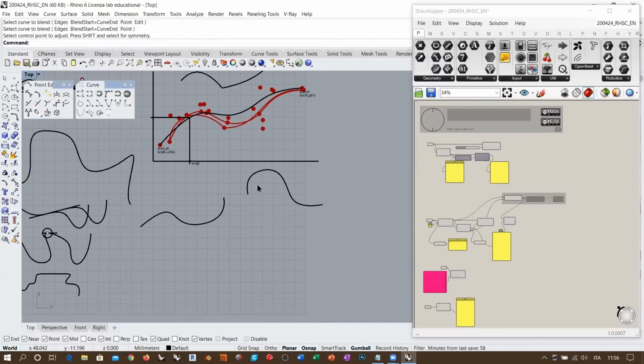So the only direct control that we have over continuity when working with the control point curve directly is over position continuity, so G0, and tangency continuity, which is G1. I repeat, for architectural design, for example, this is more than enough to define smooth shapes, okay?